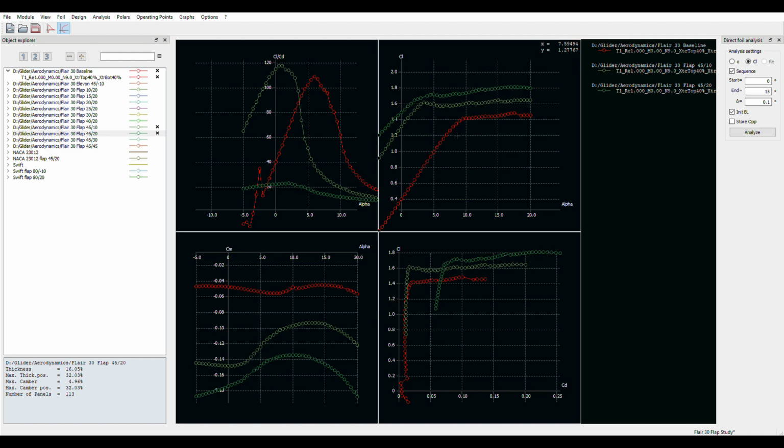Now this would not be unusual. My wing operates at about an 8-degree angle of attack on average, but my 8-degree angle of attack is 8 degrees away from a stall. He's operating kind of the same way at this point. He's got the nose back down. He's picked up some speed. He's got the glider cleaned up. He's trying to get it to trim. And he's only 3 degrees away from a stall, 2 or 3 degrees away from a stall.